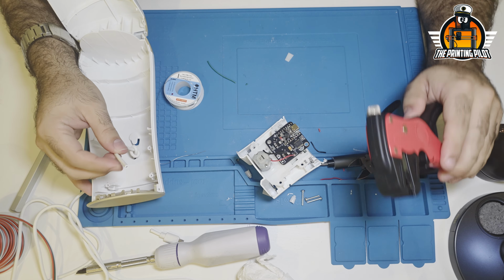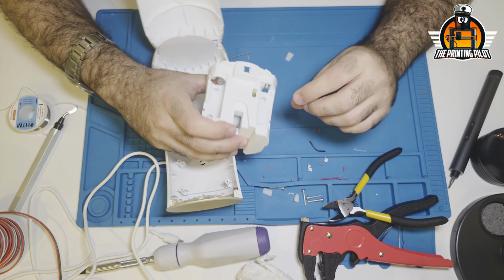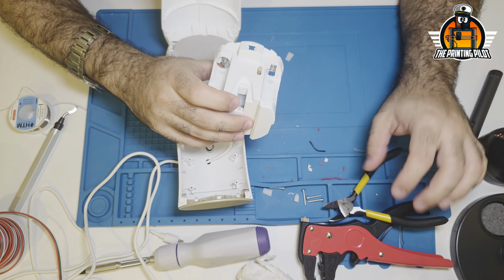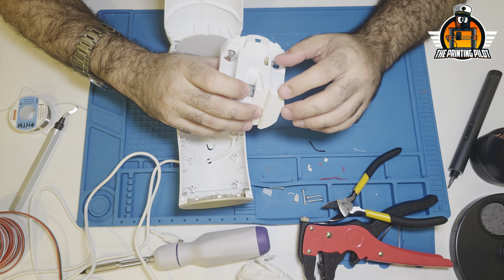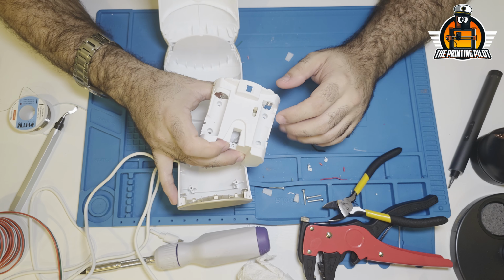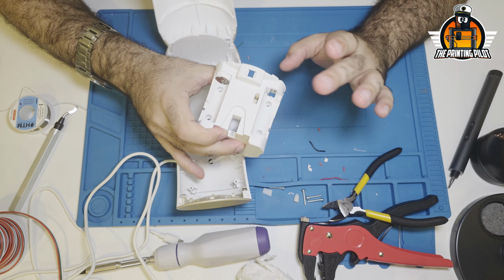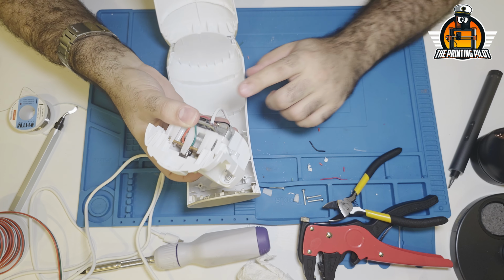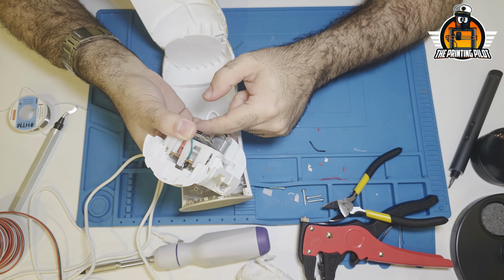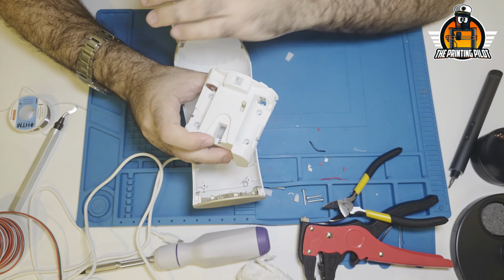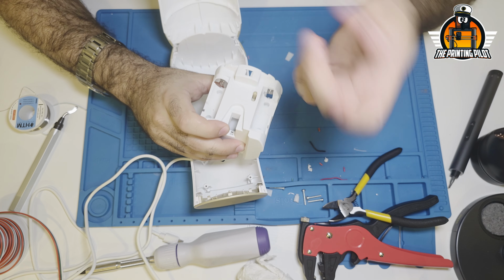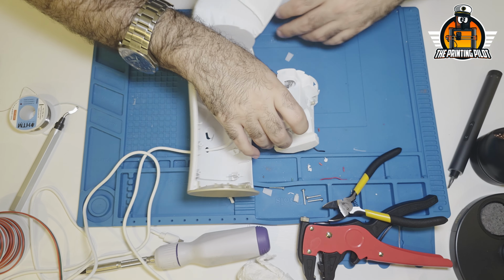So now what we have to do before we assemble everything is connect it to power and test the motor. As you guys remember, in the software portion, I told you we might have a problem that the motor is going to spin the wrong way. If it's spinning the wrong way, we're going to desolder the power connectors and switch those cables, or we can do it in software. So let's connect it to power and test it.